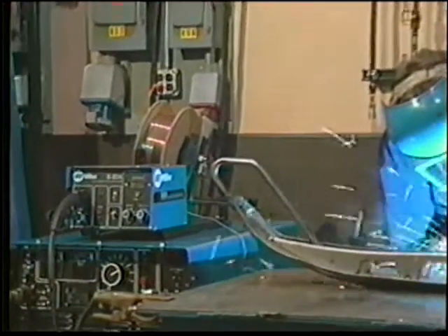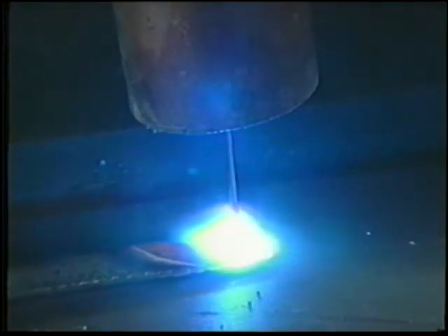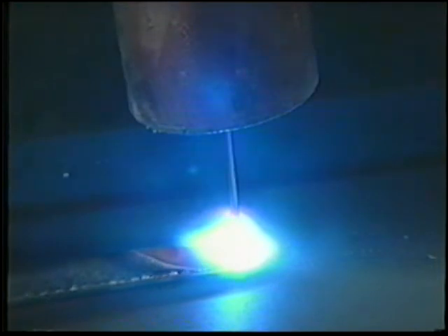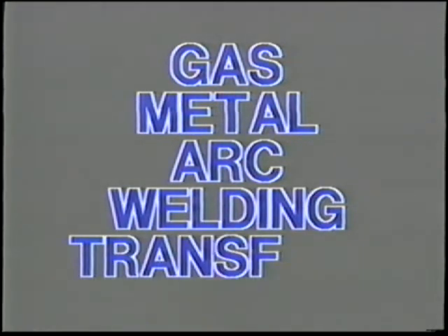In review then, the gas metal arc transfers can be separated into 4 basic modes. The short circuit is characterized by the bacon frying sound for a fast freezing puddle. The globular transfer is generally an erratic arc to be avoided. The spray transfer is a steady humming sound for high deposition, deep penetrating production type welding. The pulsed spray transfer is unique and has specialized applications. Gas metal arc welding will indeed continue to expand in various applications throughout the welding industry.